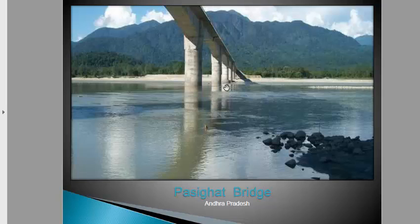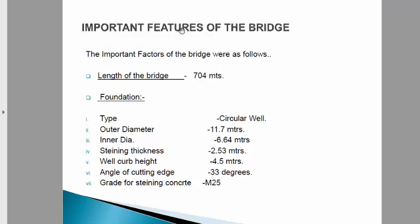So what are the important features of this bridge? I'm taking this example because you can understand the concept of the well foundation from it. The important factors of the bridge are, first of all, the length of the bridge, which is 704 meters. Foundation type: circular well is adopted because it's economical, as I also discussed in the previous slides. Outer diameter is 11.7 meters.